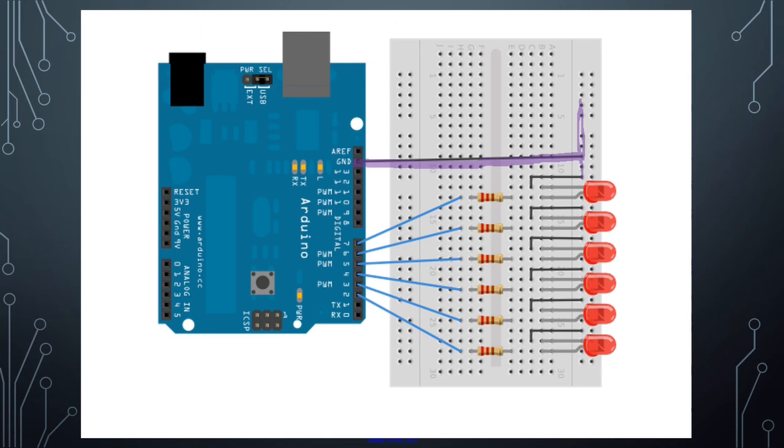And so you'll notice, as I mentioned previously, the LEDs don't have to plug directly into this ground line. We can connect them with wires. And that's exactly what we've done. So this wire now is going from that ground to connect to this row. And so here's where it's connecting to the LED. So we're not plugging the LEDs right into this ground line. We are connecting them each on their own row. And it just keeps things a little bit neater, especially when you have multiple components.